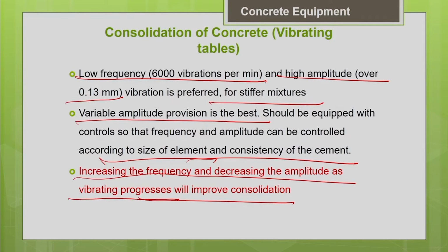If you have control over the frequency and amplitude, then you can do it this way. Generally, we start with high amplitude, and as the consolidation progresses, you start reducing the amplitude and increase the frequency. That is how we can achieve effective consolidation.